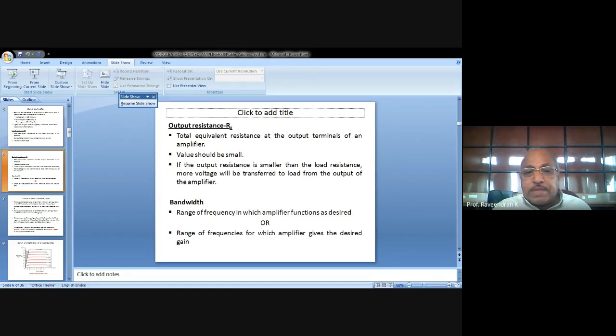Then what happens? The base current IB increases while this signal current is increasing. When the signal current increases from 0 to positive maximum, it adds with the DC voltage conditions here, so the voltage at the base emitter junction will gradually increase depending upon the variation of the signal. The resistors R1, R2 ensure the proper biasing, that is the voltage divider biasing, and the resistance RE ensures the thermal stabilization of the transistor circuit, so that the transistor's operating point will always lie within the active region.